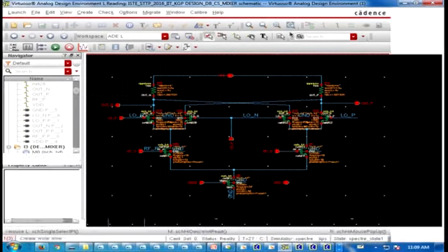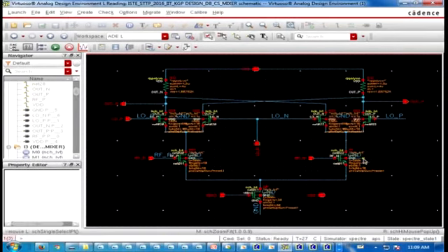Yeah. So look at here, there is some resistance, right? Those who are designing a mixer, please concentrate on this design. Whether R will be 1K or 0.8K, that actually defines the performance of this mixer.